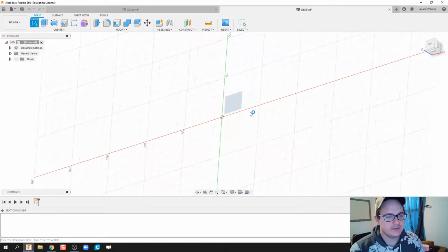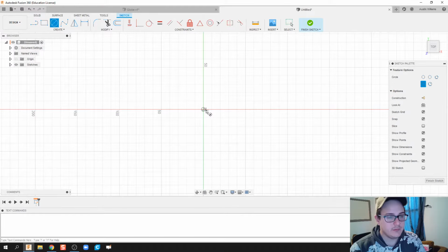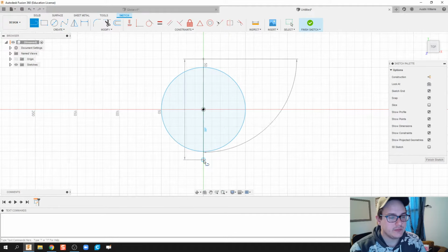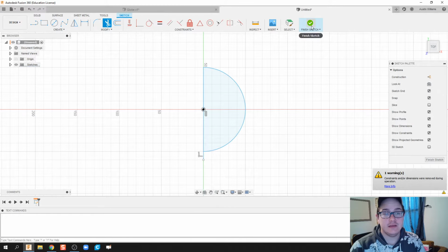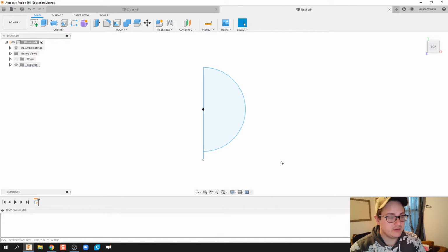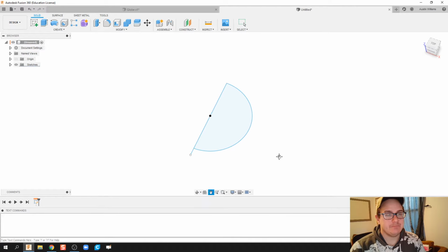So the first thing I'm going to do is create a new sketch here, and I'm just going to do my globe. Now, I know you could just have Fusion make a sphere for you, but I tend not to use commands that simplify things too much, to where the student actually isn't learning. Because once you start making trickier objects, you can't just sphere it out, box it out, or coil it out. So I'm going to show the long way.